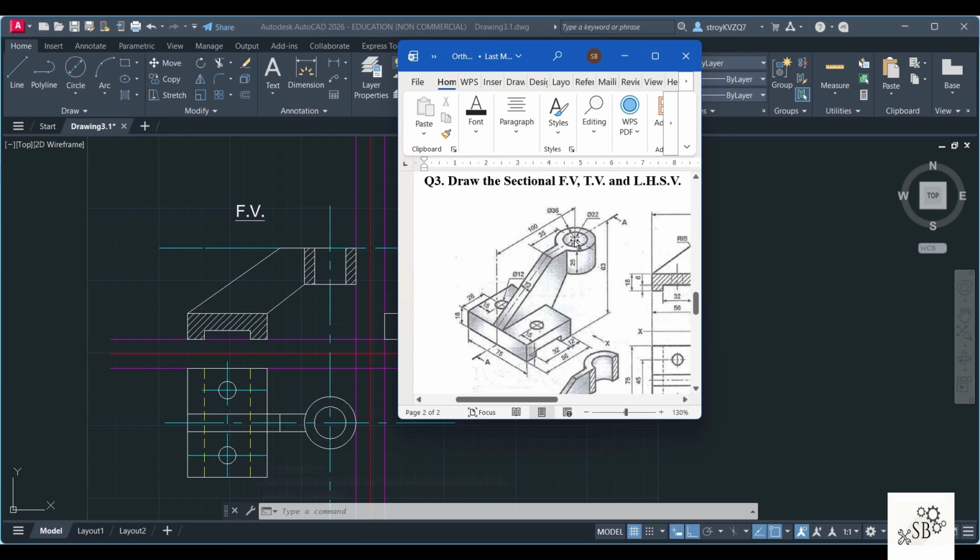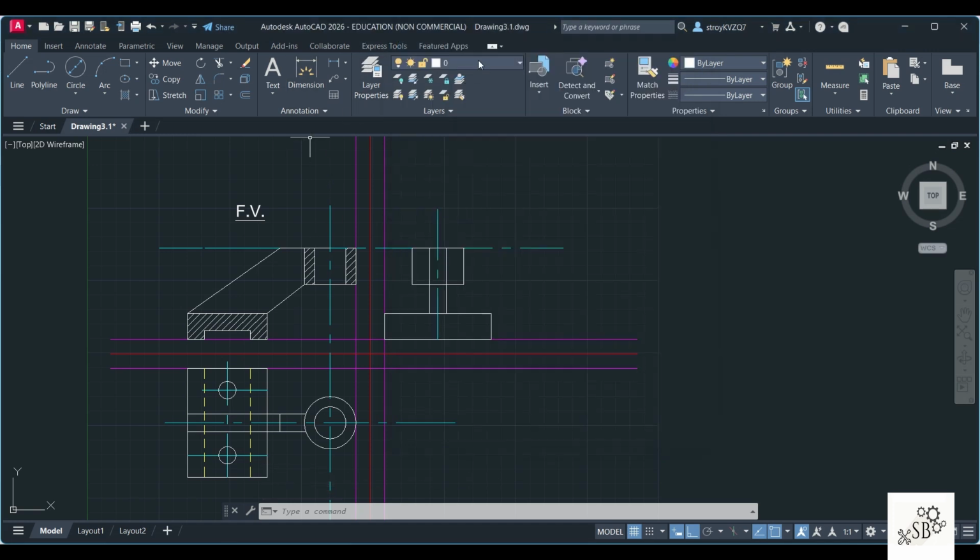Next, the inner circle here is going to be a dotted line. So I will go to hidden option, line. From here, this is 11 and then down up to this portion. Delete this line. Again, I'll mirror line, enter between these two lines.